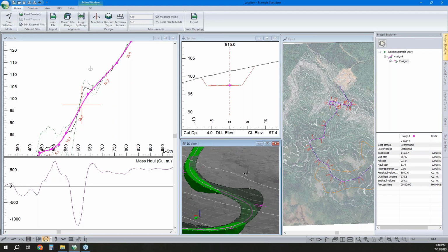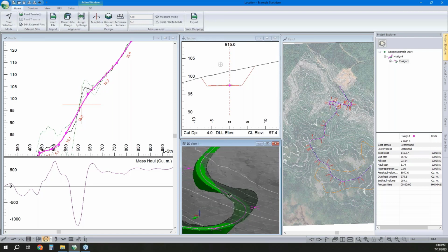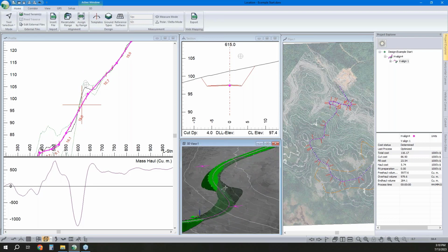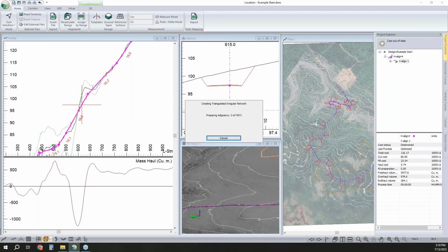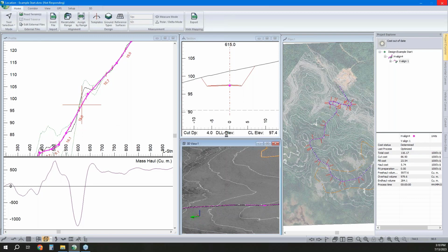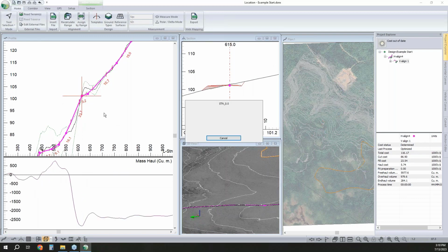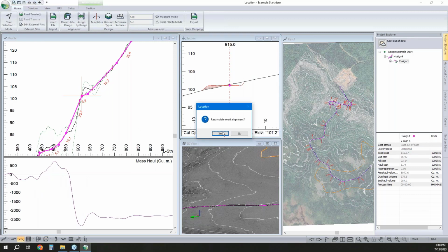So here, any water that lands uphill here is going to, as is, land on the slope above, come down, hit the road and we'd have water channeling on our shoulder rather than just being stored off to the side in a ditch. I'm going to jump to somewhere flatter here. Oops. I'm going to hit undo. I hit the wrong button.